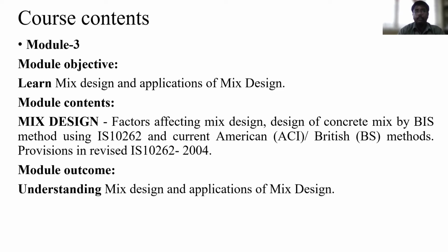In the concrete design process, there are several grades of concrete starting from M5, M10, M15, M20, M30, and M35. We are mix designing these concrete mixes according to the Bureau of Indian Standards code IS 10262, and also we are using the American Standard Code and British methods for the mix design process.